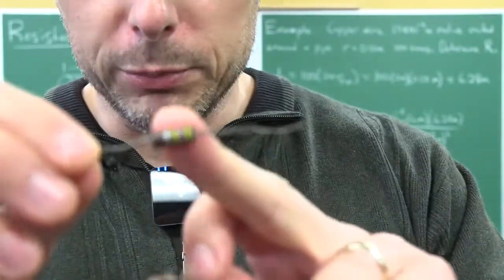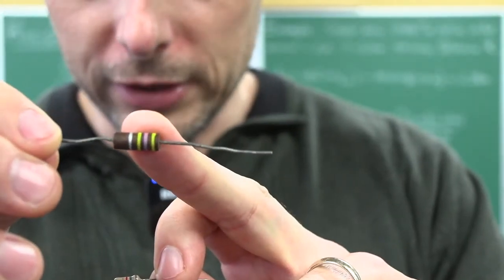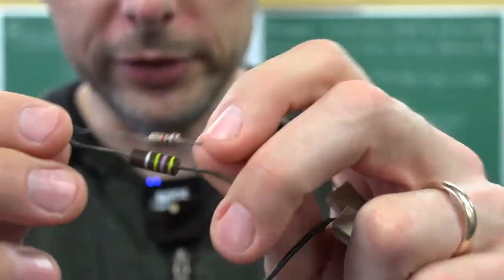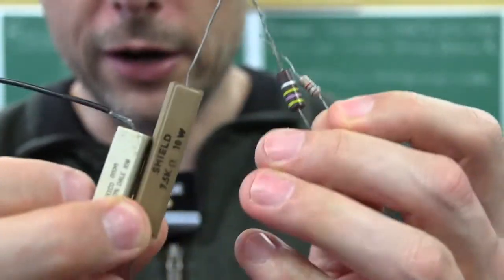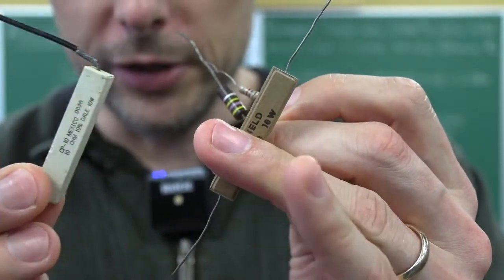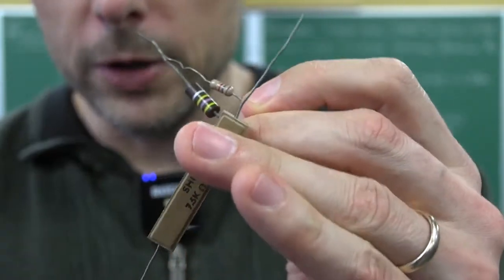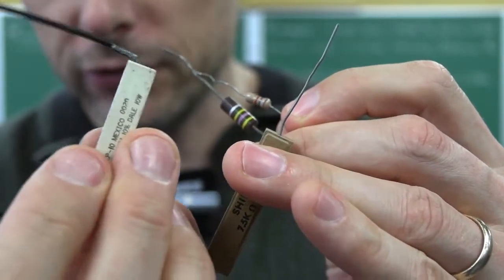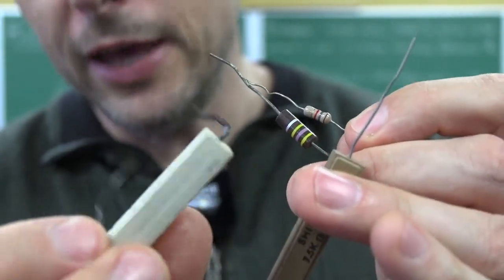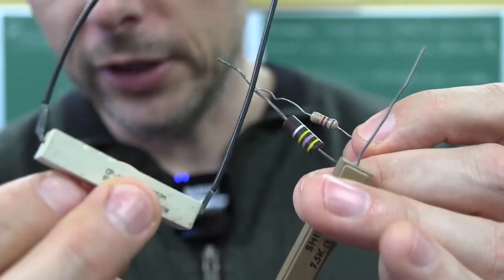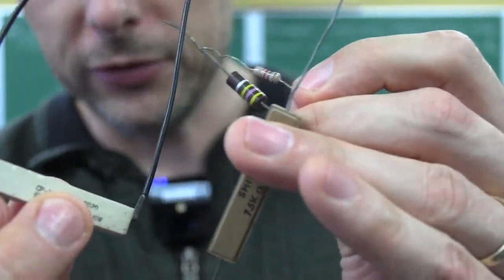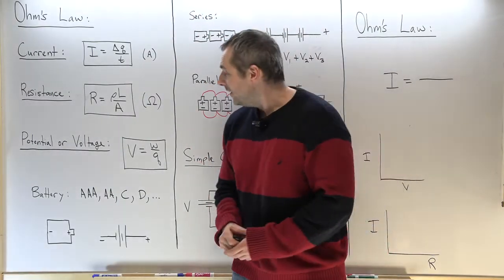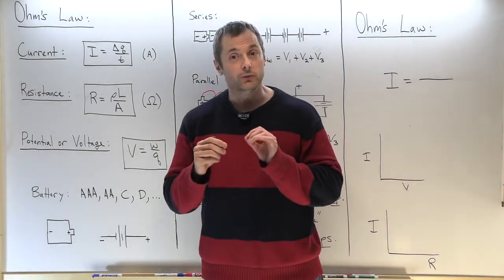Sometimes if they have a pretty small resistance and to allow them to have more current in them, they can be a little bit bigger. Okay, so that's a possibility. And sometimes you can buy resistors that are made in ceramic material if there's a lot of current going through. So this is a resistor that I have for a lab in Regents. This is approximately 10 ohms, and because it can heat up so much, it's got all that ceramic material. So you see a couple different kinds of resistors. All right, so there were some examples of resistors.